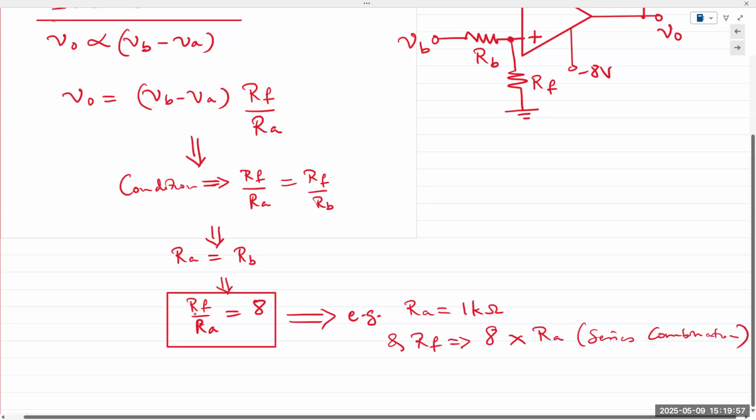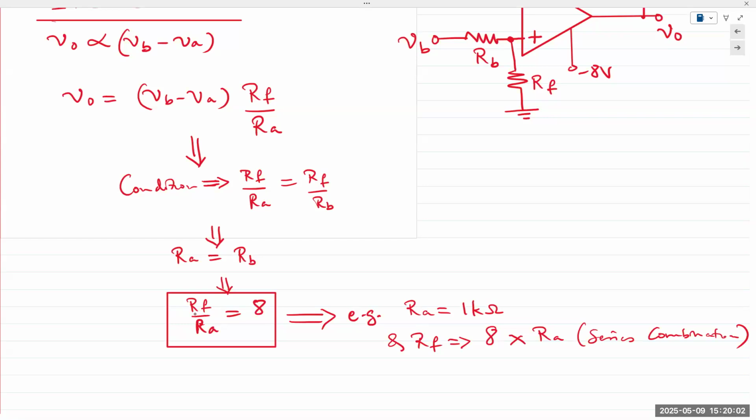Okay. The consistent theme in all of these design problems is we have a standard equation for the gain. Look at our output. Depending on what our output is, we choose a value of one of the resistors and then we calculate the value of the other resistor. So again, this is design at its lowest, most simplistic level. We're simply taking the gain. We're not accounting for anything else.